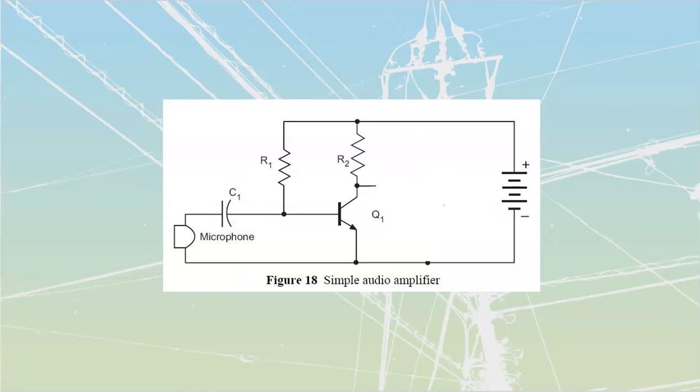Okay, so I'm just going to erase this one here, and then erase this section over here. What do we have? We have just a standard transistor type of circuit. A couple of things that we should know about this transistor circuit. We know that for certain, we are going to have a voltage drop of 0.7 volts. That's going to be across here, which means that we're going to be dropping the rest of whatever my voltage was over here across that, whatever it is minus 0.7.